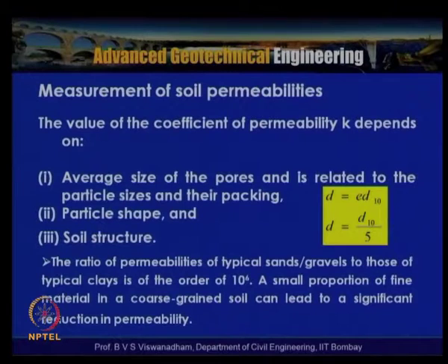If you take the effective particle size of a sand and of a clay, clay has a very low effective particle size, so the pore diameters of the clay are very fine compared to a sand. It is approximated that 20% of the effective particle size is regarded as the pore diameter.